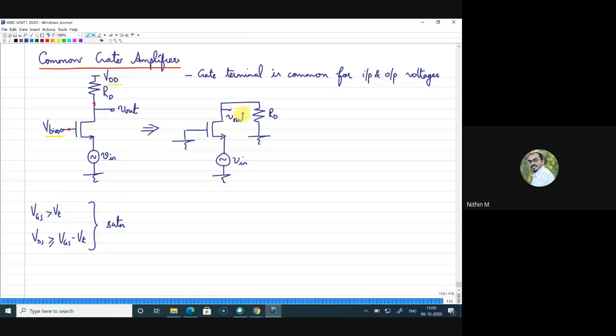This is the small signal picture, and for this circuit we are going to draw the equivalent circuit. How will I draw the equivalent? First I'll keep the equivalent of the MOSFET. These are the three terminals. This is the gate, with plus minus VGS. We will have the current gm VGS flowing in this direction. I will not consider lambda initially; we will deal without lambda.